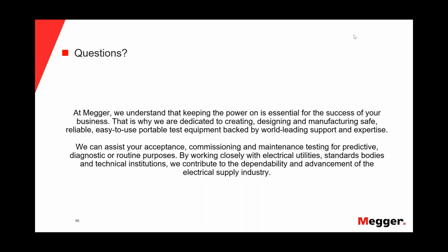I think you have certain defects that are much more sensitive to, let's say, 60 hertz. I would call it power frequency, because power frequency, which means 20 to 300 hertz, has been proven equivalent to actual power frequency at 50 or 60 hertz. So I just want to say power frequency versus 0.1 hertz. Certain defects have shown higher sensitivity with power frequency than at 0.1 hertz. So overall, from a technical point, I think it's preferable to do PD tests with power frequency compared to 0.1 hertz.